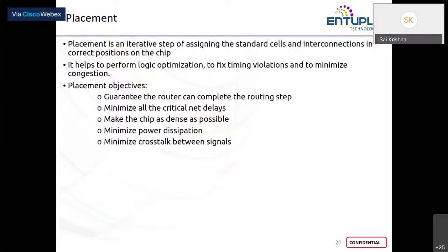Okay, but it is from placement where the efficiency or the quality of your physical design can be determined in terms of timing, area, and power. Please note that at floor plan, you start with utilization somewhere between 50 to 70%. Let's say, just for our understanding, that you started at 60%. After floor plan, you have come to 65%.